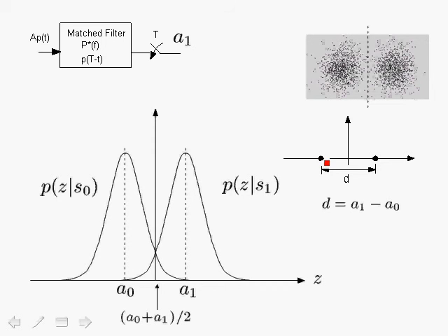Here we show the actual symbols that are sent in a constellation diagram, but basically this is the symbol corresponding to A0, and this is the symbol corresponding to A1. At the receiver, we receive these signals with additive noise effects, so that the signals that we actually receive will not be at the ideal point, but would be scattered about.